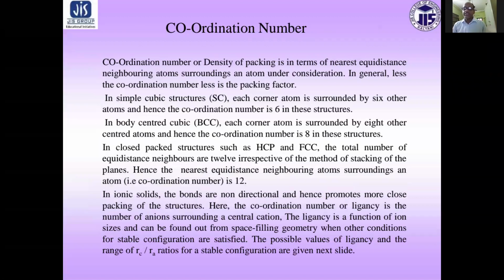So next is what is called coordination number. Coordination number, or density of packing, is the number of nearest equidistant neighboring atoms surrounding the atom under consideration. In general, the lower the coordination number, the lower the packing factor.